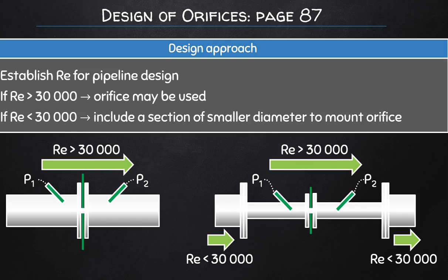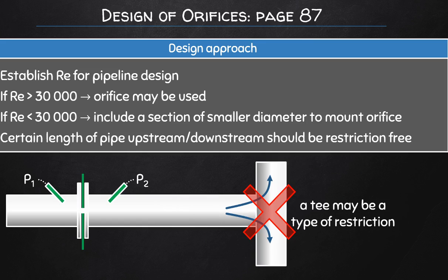Okay, but remember, as most flow meters are sensitive to flow, it is very important to choose your location correctly. So for example, if you have a downstream T that is very close to a flow meter, this can cause disturbances in the readings, and an erroneous flow measurement can result. And so you think the flow is one value, but in fact it is another value.